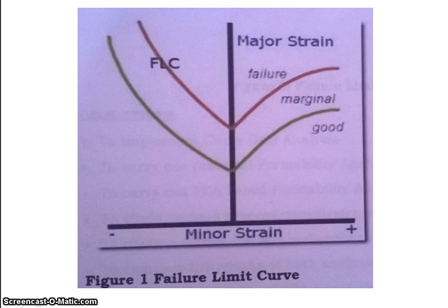A die or lubrication change is generally required to remedy such problems. Points that fall in the undefined region should be replotted with the major and minor strains switched. The shape of the forming limit diagram is approximately constant for all the stages. The curve moves up and down the major strain axis as a function of the steel sheet characteristic.